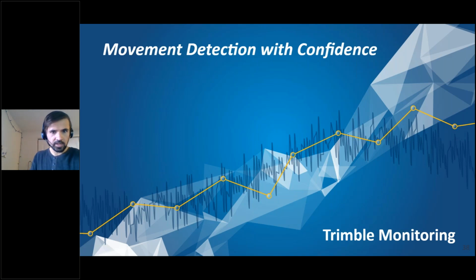All right, question here: is it possible to upload data such as traverse and rounds of different measurements through a text file? Yes, it is, as long as TBC can support that file format. So a good example is if I have points defined in a CSV, I can import that into TBC using the import format editor.